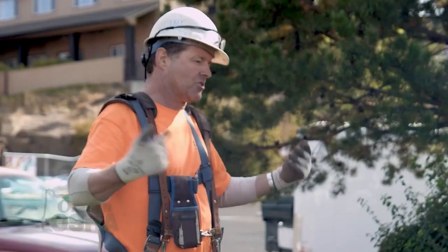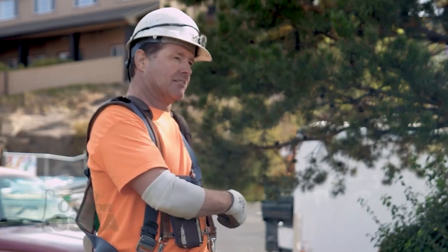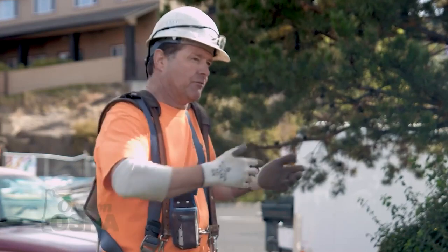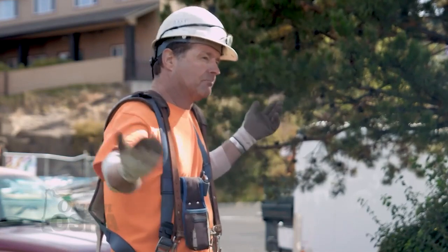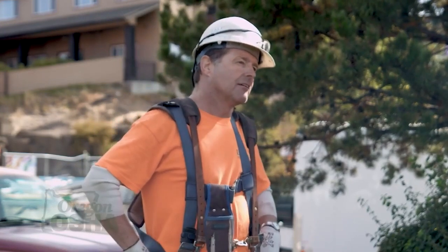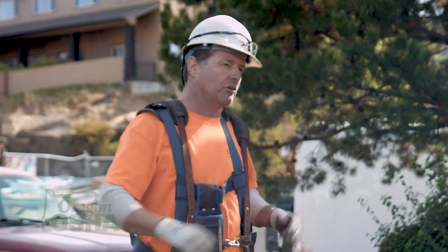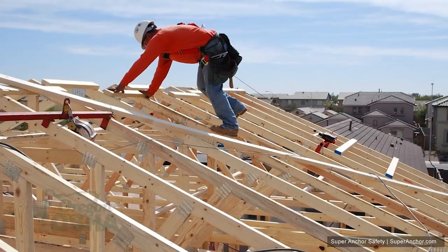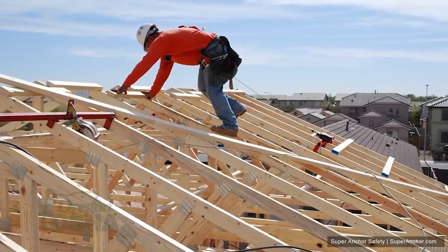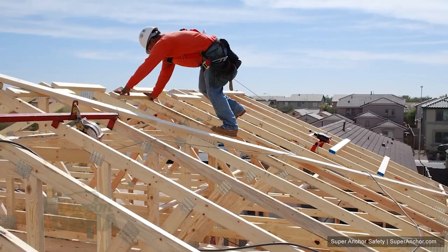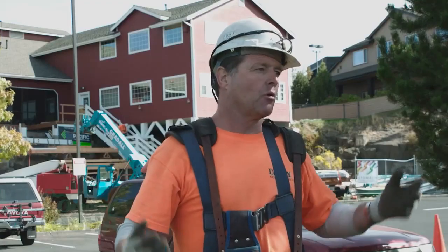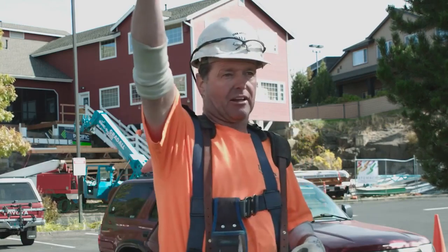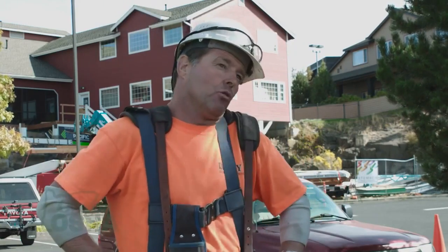And during that time, you're tying off to the top plates, and you can't really go very far because, if you go out too far and you're up 10 feet or 9 feet, then you're going to hit the deck if you fall. So you have a very limited radius. But once you have a certain amount of trusses rolled, then you can brace them so they're sturdy and could withstand the impact of a grown man pulling on them. Once they're braced and stood, then you can put your retractable up higher, and then you can roll your trusses.